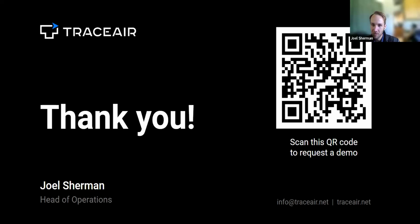Does it differ significantly from photogrammetry? I'd say it's about the same. There can be a little bit less from our perspective, but they're pretty much comparable. If you're using RTK or PPK, the density of the network can be pretty much the same. When you're using non-corrected imagery, then yes, a significant volume more of GCPs would be required.